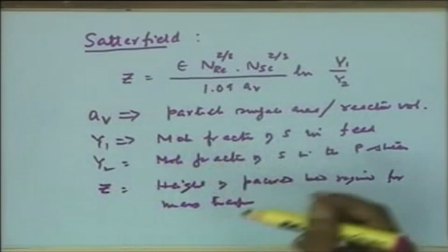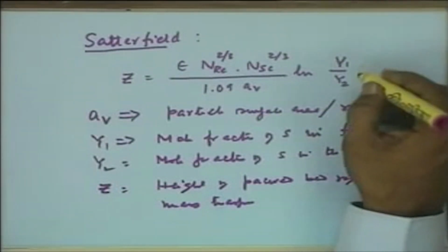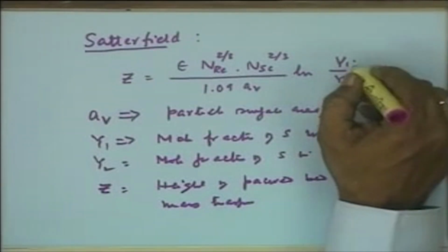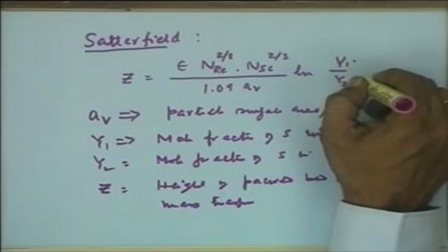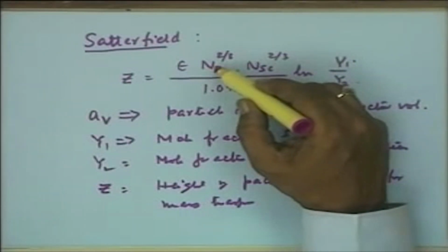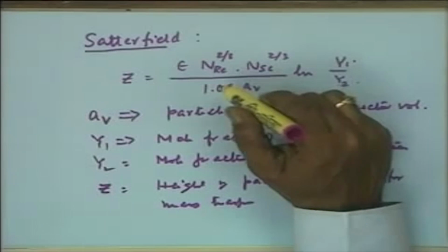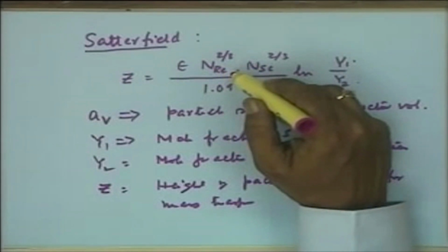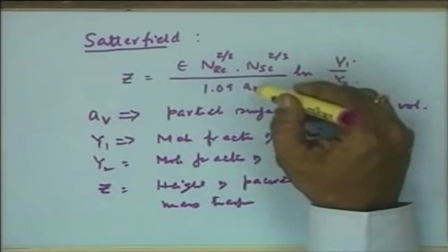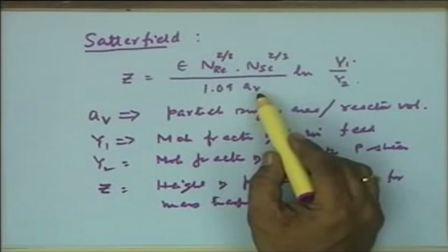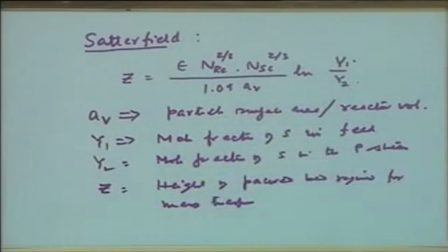Now, obviously, based on the operational data, that means the concentration of substrate in the feed and the product stream, as well as the parameters of the reactor operation and the particle morphology, the particle size, one can determine the length of the reactor required, and compare it relative to the length of the reactor required for biochemical reaction.